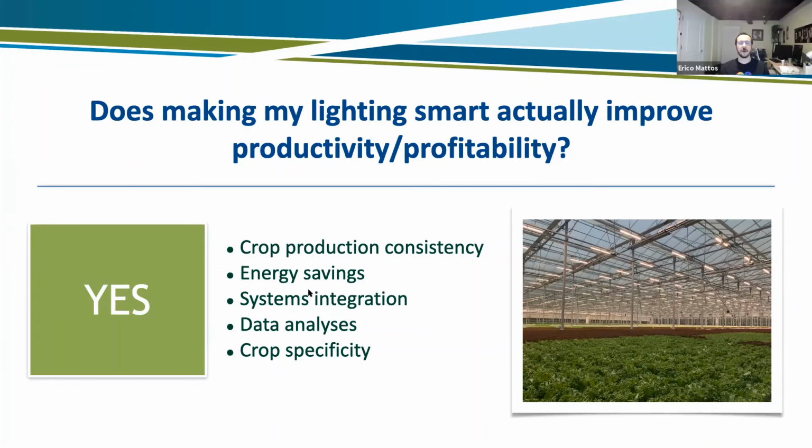Great question, John. No, I think the technology makes it available for any grower, from a single home grower to a very large installation. You find smart lighting controls for everything you do. You have dimmers, timers, adaptive lighting controls, threshold controls, and we can talk about how each one of those works. But there is a solution for everything out there. If any grower has the money to invest in a lighting system, they should make the investment in a lighting control system. The most basic controller will give you 10%, and the most advanced up to 50 or 60%, compared to having no controls at all.